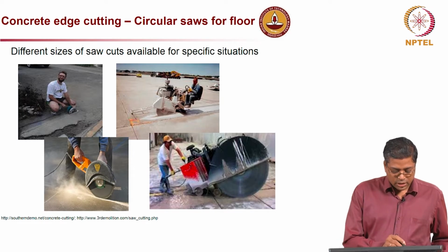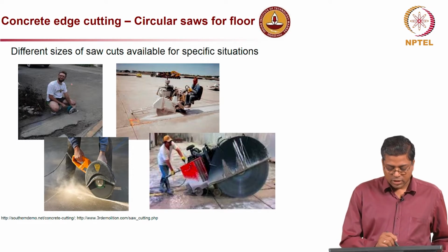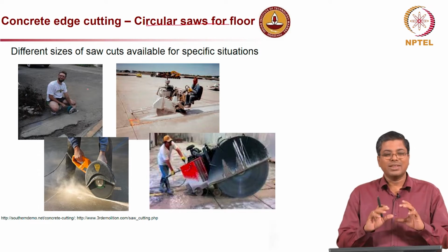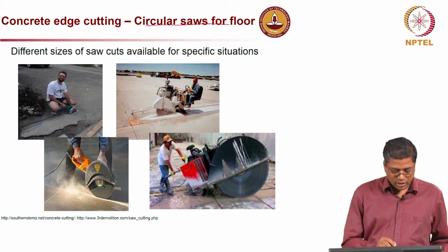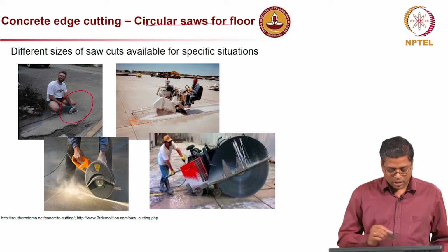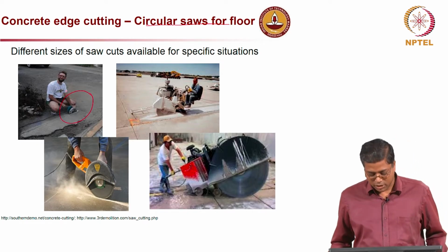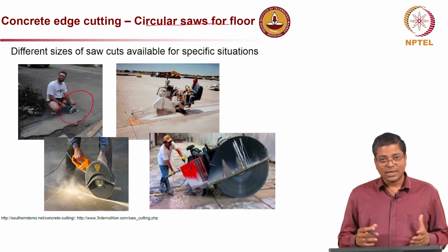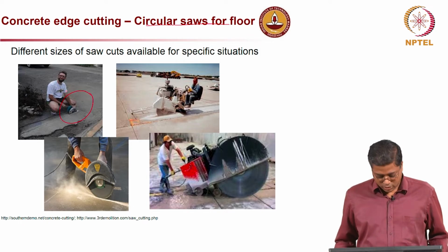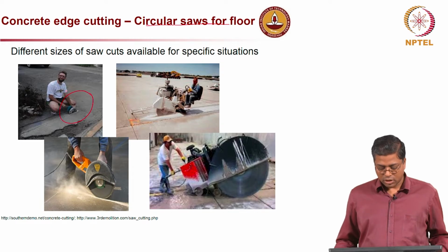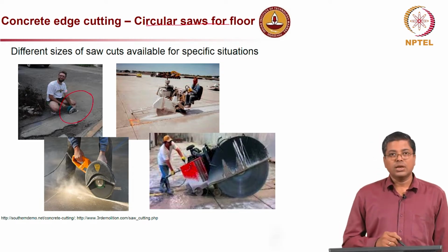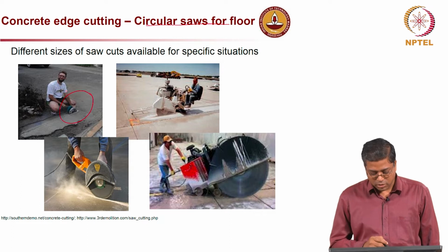So, you can see different sizes of circular saws are available. If you are talking about very thin concrete cutting, a typical circular saw can be used, depending on the thickness of the concrete floor. I am really showing tools for cutting floors here.